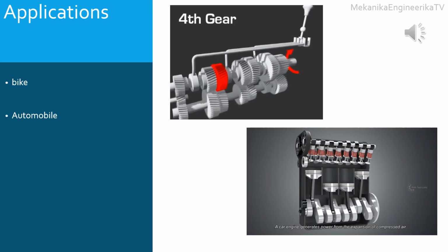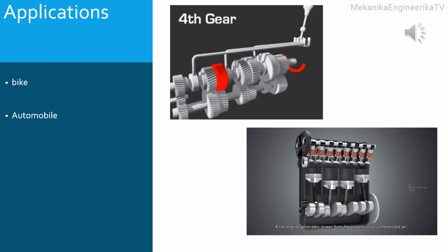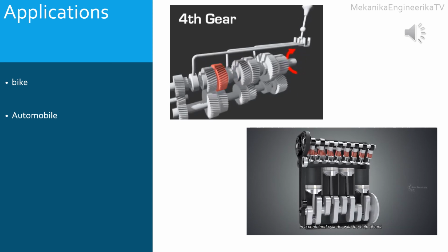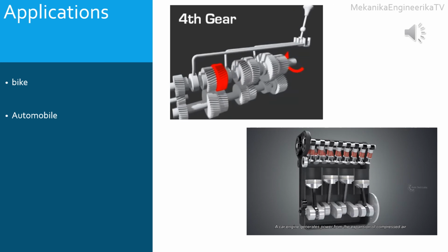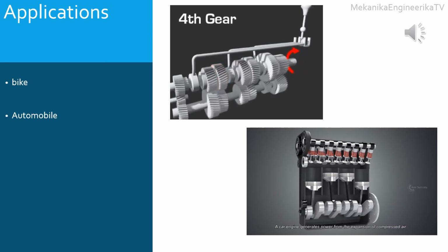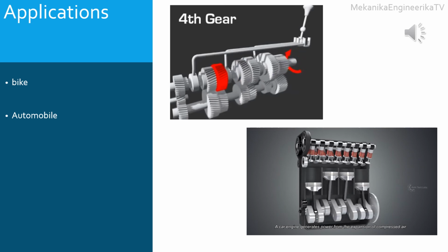An automobile involves several mechanisms. The gearbox is an example of these mechanisms. Manual transmission systems use compound gear trains to provide torque multiplication. Also in a car, the gas engine uses slider crank mechanisms to transform the reciprocal motion of the piston, induced by the gas explosion, to a rotational motion.